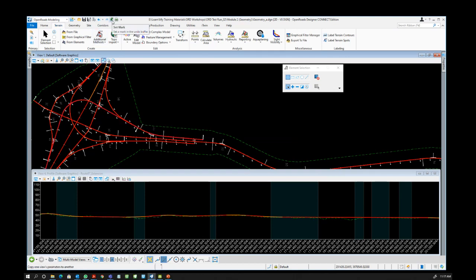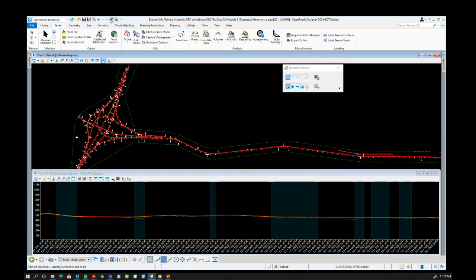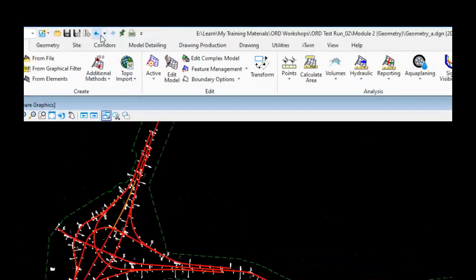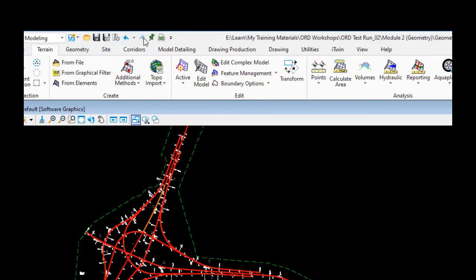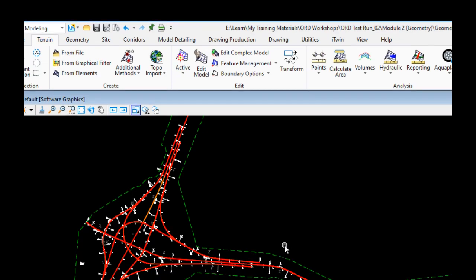How do we mark? Let's say I'll set this as my mark. So you see this button up here. This is the undo button. This is redo. Then this is mark. So meaning to say, you're marking your file so that any edits that you would do would undo to that point. Okay. So let's say I mark this file.